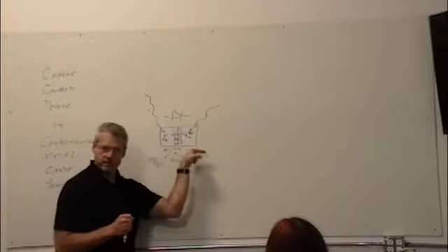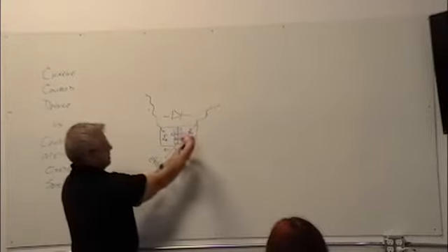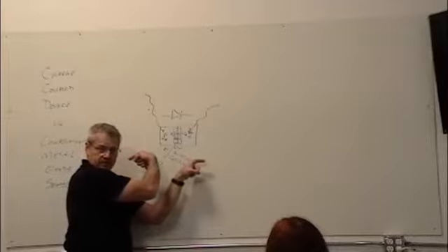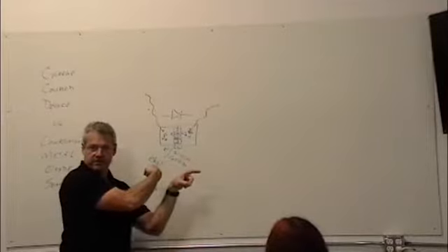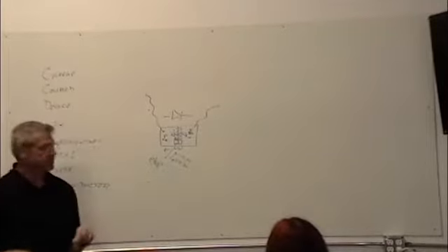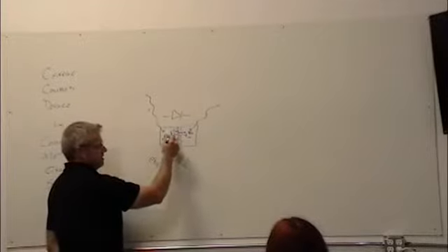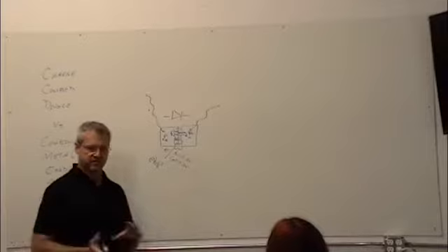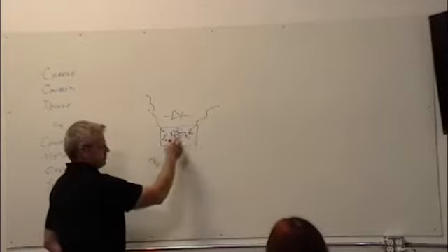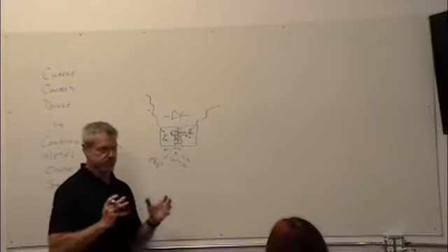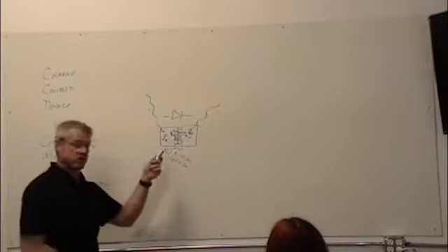swept one way, and an electron is swept the other way. Now eventually those are going to recombine, but they're going to first come all the way over here and create a difference in potential, and then eventually they'll work their way back and find a place to recombine. That's how a solar cell works.